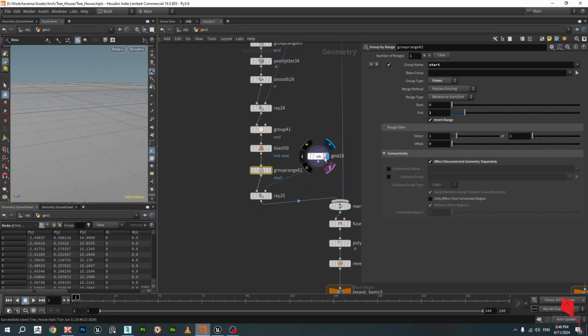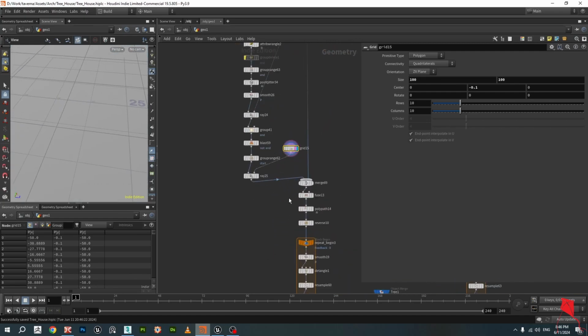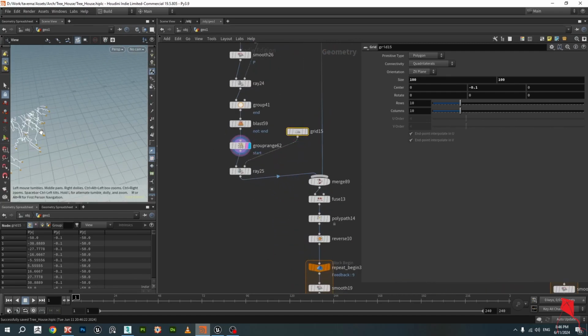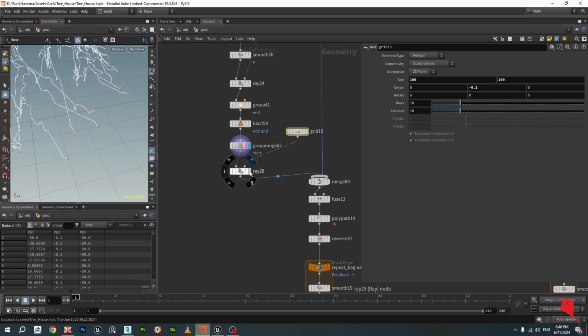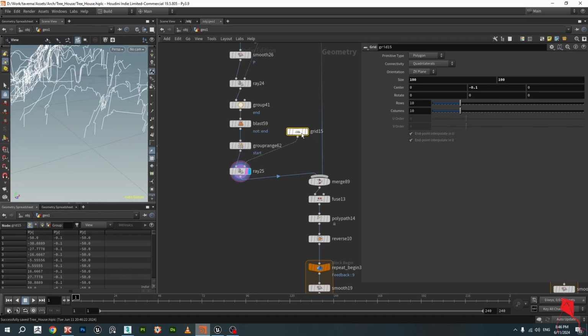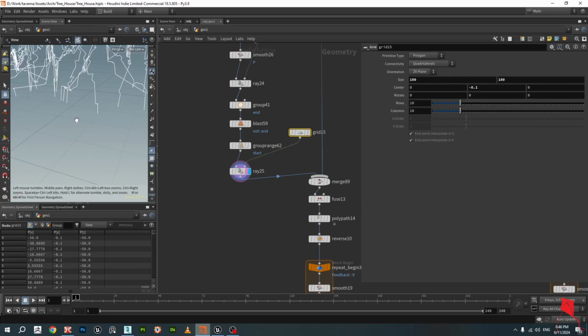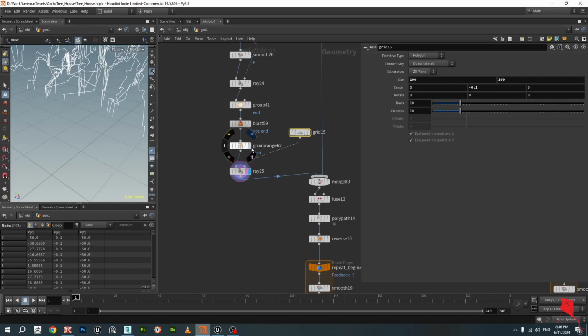We create a grid that serves as a floor. Could actually reference the grid from up there, I just wanted more clarity. So like this, and then we project them down again. And actually, this grid, that's why I could not use the other one. It's located not at 0. It's located a little bit below 0 because we want them to dig into the ground a little bit in case we have a landscape change, shift, or something. So we want them to dig in, and that's what happens.